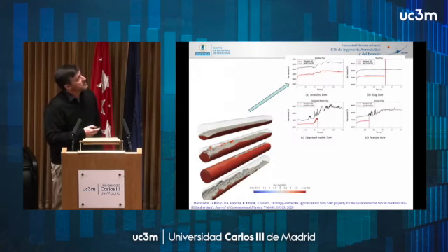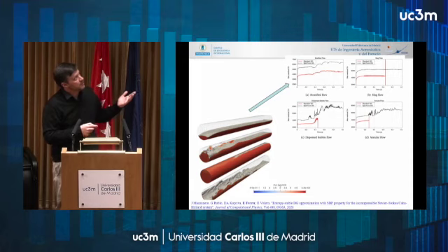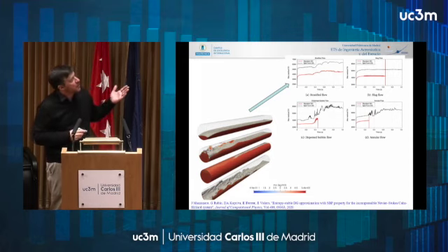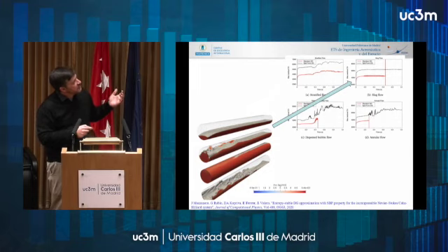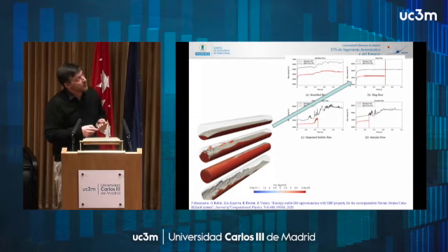So then what happens is that, okay, if we have a very smooth interface, as in this case, the normal solution and the entropy stable solution work perfectly, you get good solutions. However, when you start having sharpening at the interface and you have some lack of resolution, and you start having aliasing errors and building up of energy, if you're not careful, things blow up.